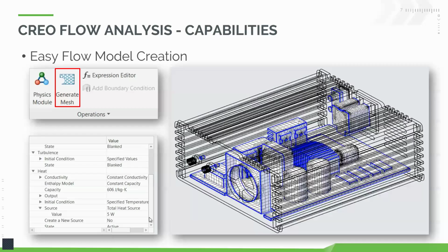And with the way that you define this, the system allows you to either set up the mesh yourself or you can have the system generate it for you. So even if you don't necessarily know how to overly define the mesh and do that manually, let the system do that for you. You can always tweak it if you need to, like if you have areas where you want to refine the mesh or you want to lightweight it, you can still refine that yourself, but let the system do all of that complex work for you.